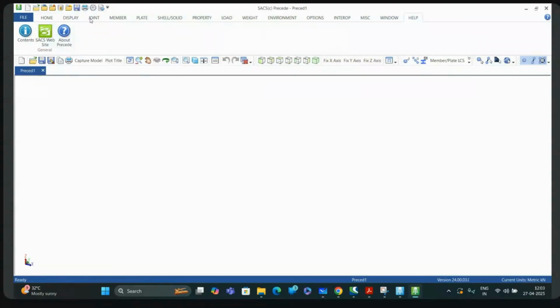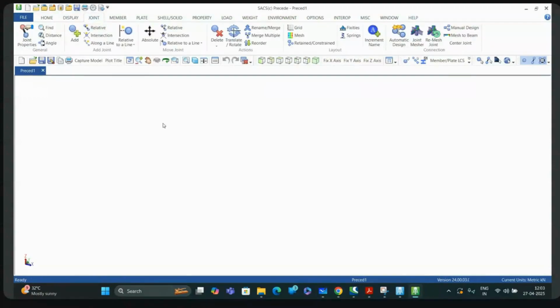Now, have you used STAAD.Pro? You three are from civil, right? Yes, sir. Okay, so if you have used STAAD.Pro, this is almost similar to STAAD.Pro, so it will be very fast for you to understand. In STAAD.Pro, how will we be designing it? First, we will be creating the joints. Then we will be creating member properties, and then we are assigning members. Then we are assigning boundary conditions. Then we are assigning loads and doing the analysis, right? Yes, sir. Yeah, this is almost similar.